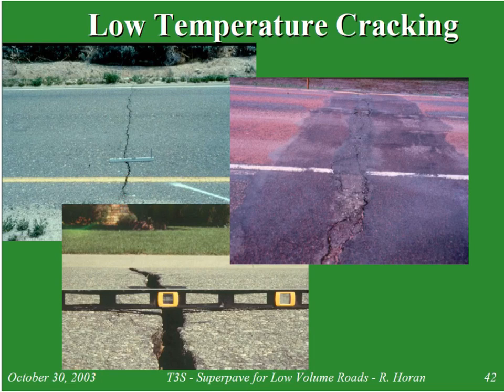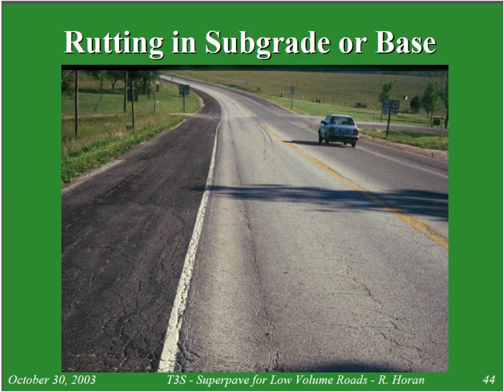As it shrinks and becomes more brittle, it'll start to form cracks. So cracking is a result of low temperatures in the asphalt. The asphalt is trying to shrink and pull apart, and that creates this type of cracking. So that's one conclusion of the SuperPave program.